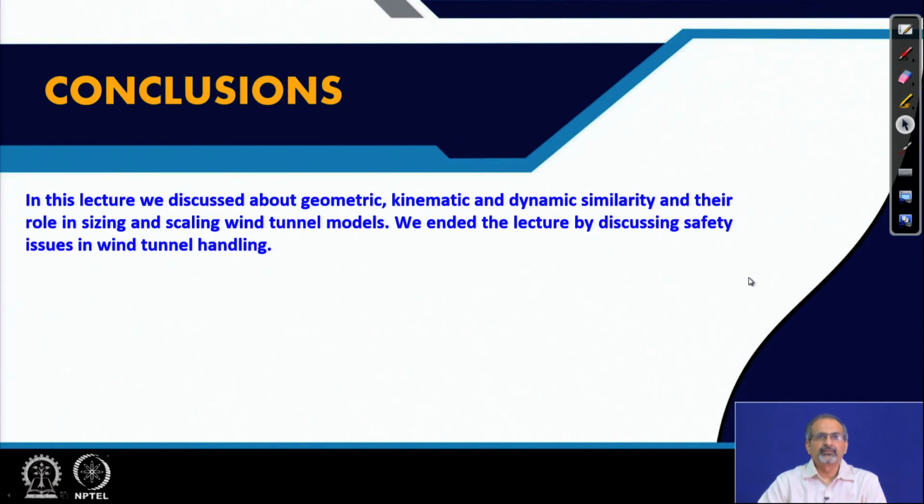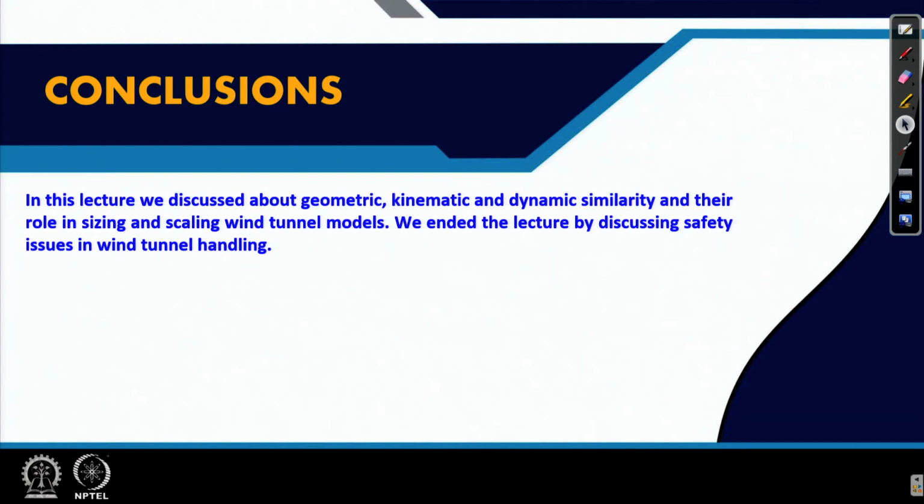So, in this lecture we discussed the different kinds of similarity, including geometric, kinematic and dynamic similarity, and their role in sizing and scaling of internal models. We ended the lecture by discussing safety issues in wind tunnel handling, both for low and high speed wind tunnels.